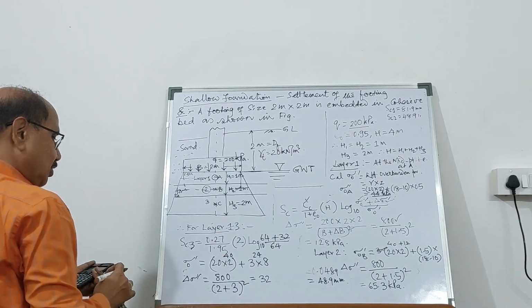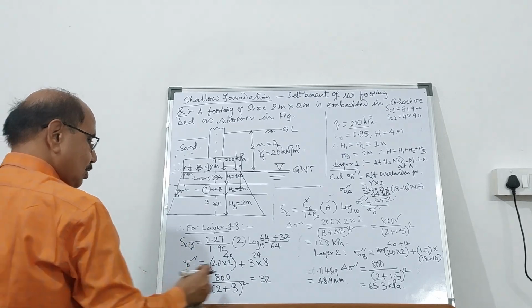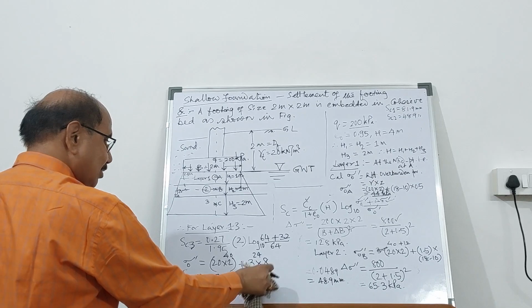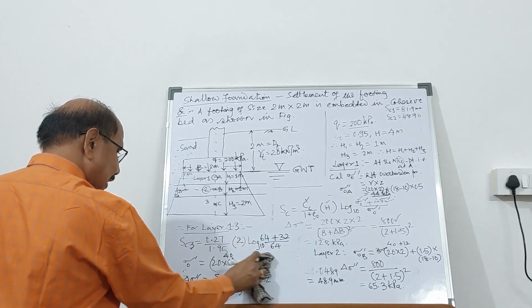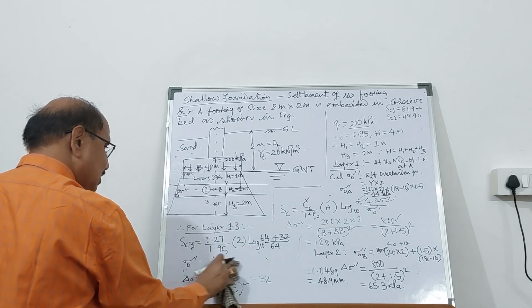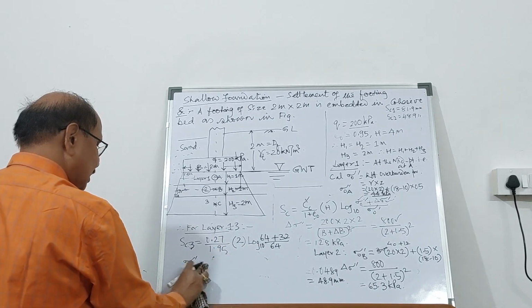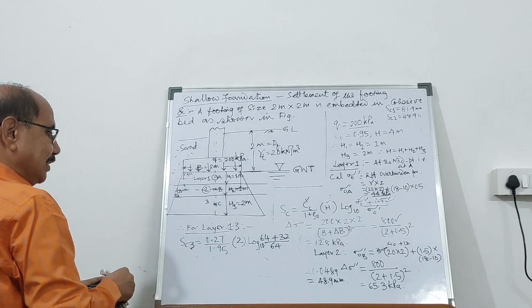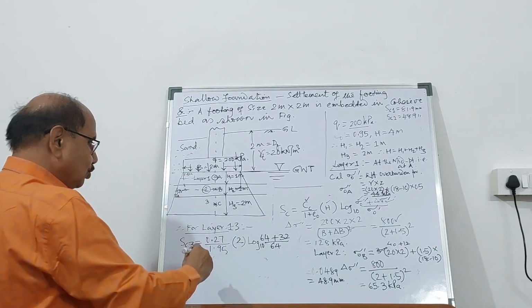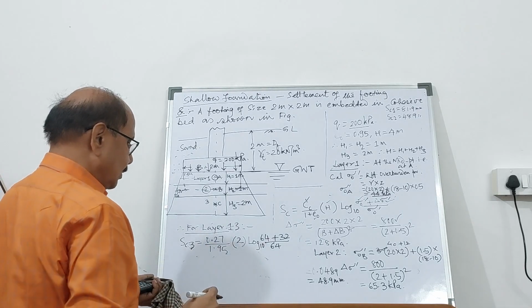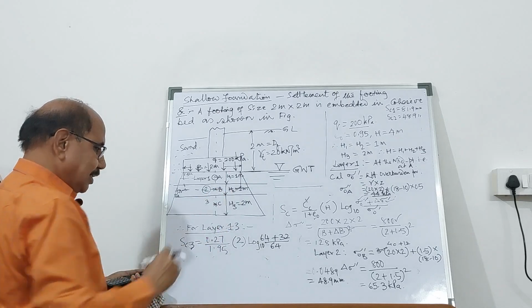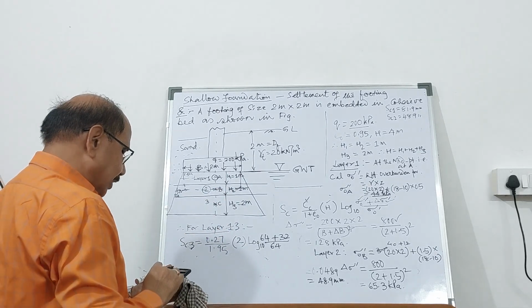So you see how you have been able to calculate and see the reduction in the value of delta sigma as you go deeper. It becomes substantially less. In the first layer, it was very high, 128. It has come down to a mere 32. So that's why you have to go 2 times B, and that has to be divided into 3 layers.